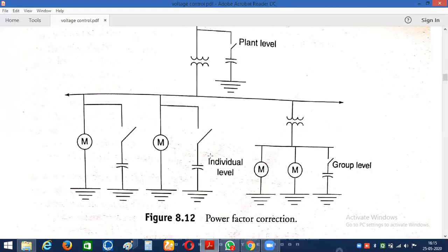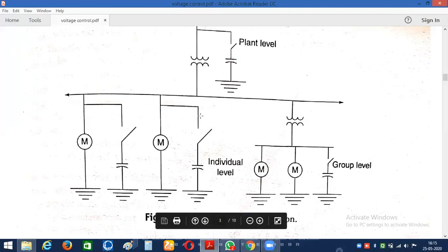So this is how shunt capacitors connected in parallel to the load act as a reactive power source, not only controlling the voltage at the receiving end. Why? Because if you do not have any capacitor banks, all the loads connected to this particular bus continuously take reactive power, resulting in a lower receiving-end voltage towards the last end. As you go further, the voltage level decreases. The last-end customer on the same bus gets a lesser voltage compared with the starting customer. To reduce this effect, the shunt capacitance can be used easily.